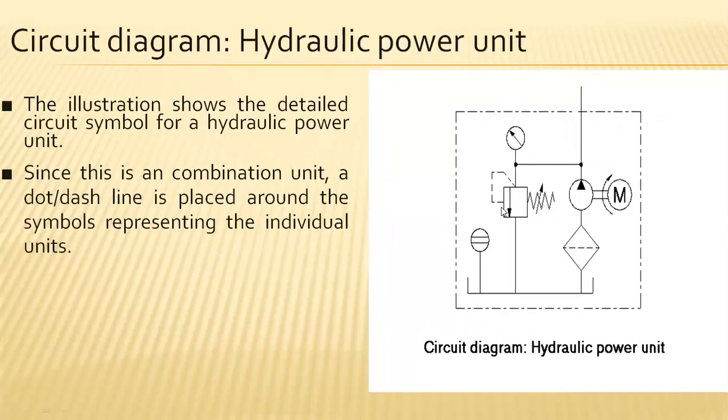So this is a component or circuit diagram related to the input system, because after crossing this motor by imparting a particular pressure, it will be entering into the directional control valve, which directly passes the fluid to the actuator for its movement, causing the movement within it, either in forward direction or else in the return direction.